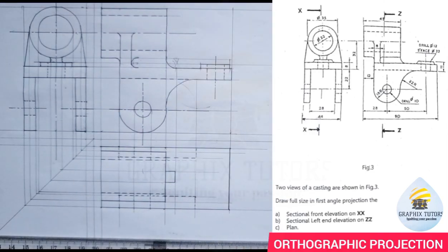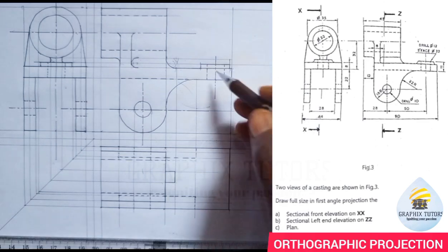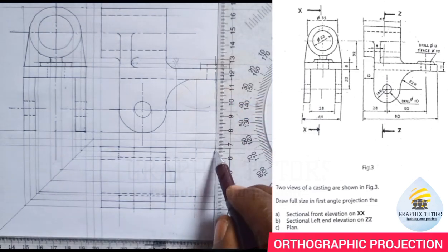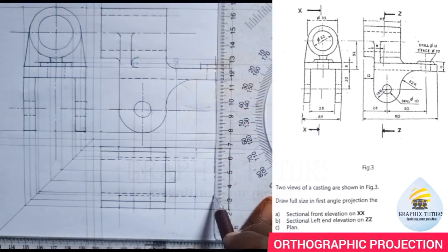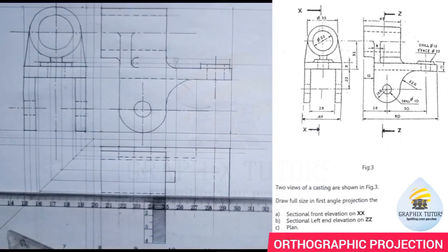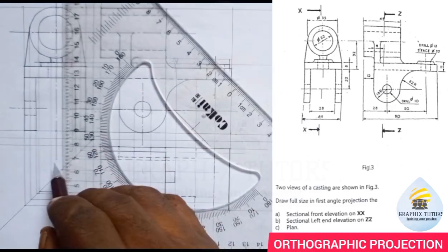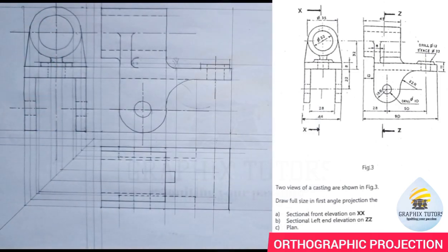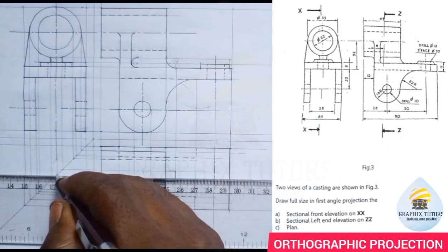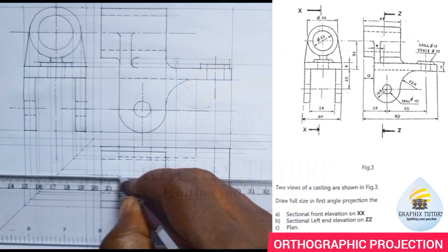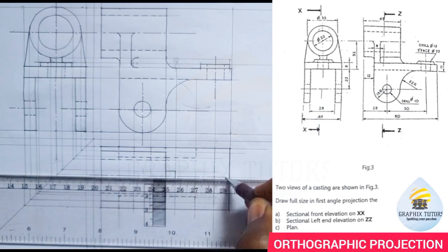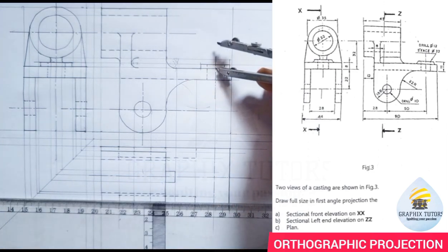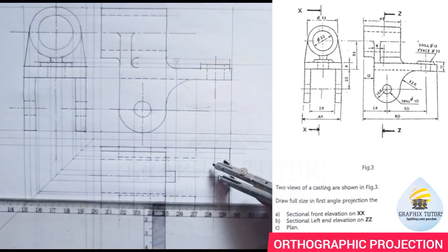So aside that, the next thing is this you're seeing here, you're having a circle here. So when I bring this down, that will be a center line. And here also, bring this down also. That is the center line. I'm bringing it here. So here is also center line of the given figure. So they are meeting here. So I can easily just take the radius of this circle here, or I can easily project them down and I will draw my circle.